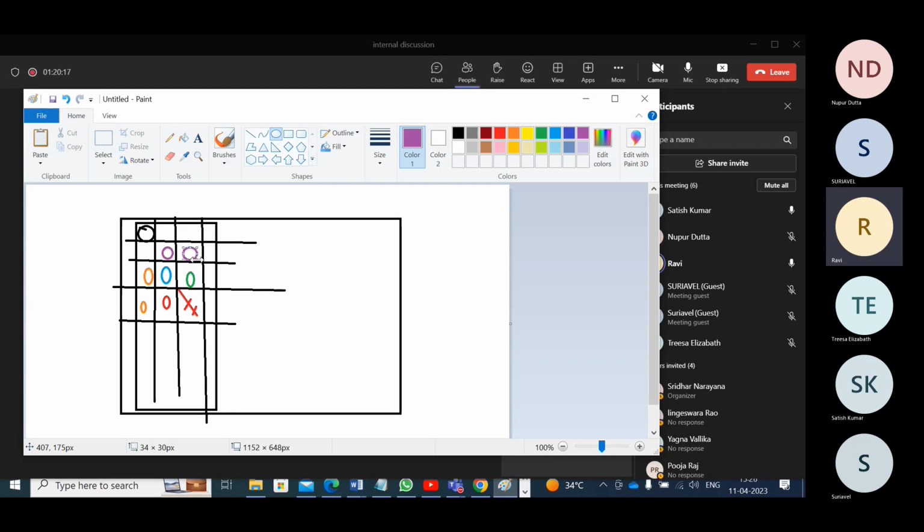Next, that's the question: net length reduced? If the answer is yes, move it. If the net length is not reduced, keep it. If the net length increases, keep it. Then move to the next one. Should I move this? Yes, no, like that. Which are my modules? Which are my hierarchies? Where should I optimize? So that's the way it does its own work.